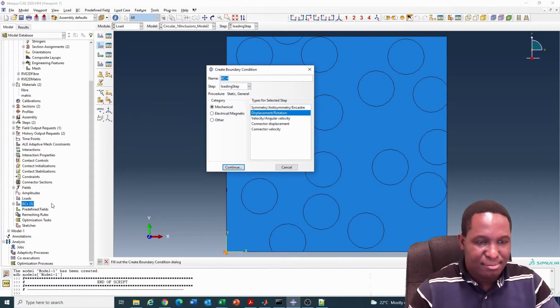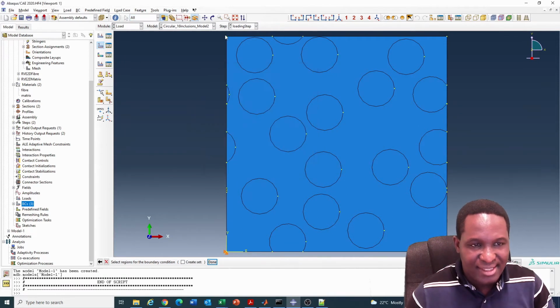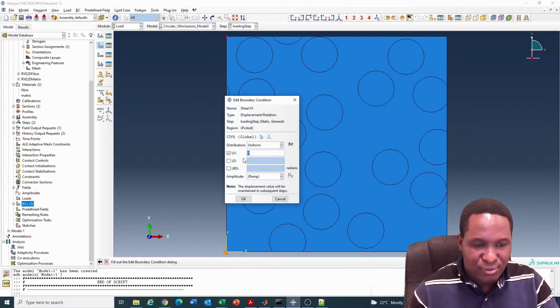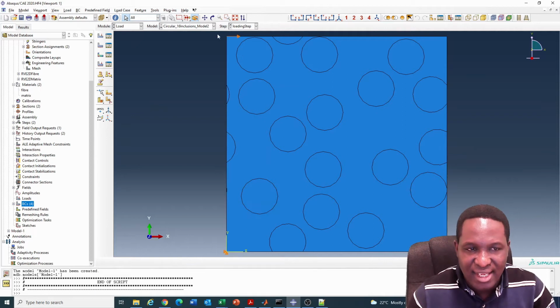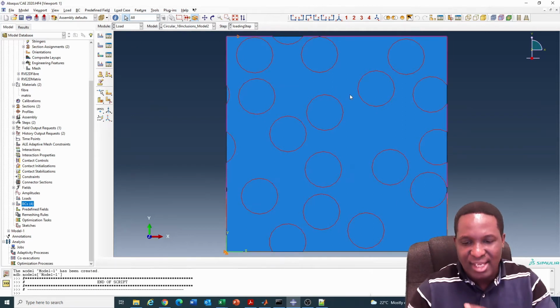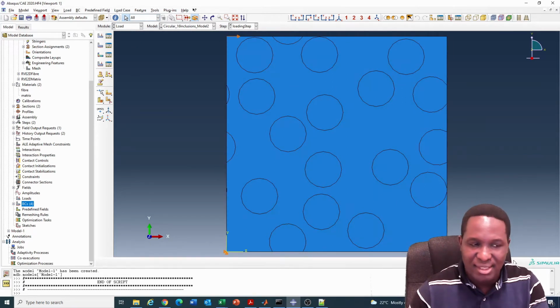Then the second shear component will be shear in the YX direction. This will be acting in the X direction, and it will be a value of 12. So if you think about what we've got here, we've got a case of pure shear and a tensile pull on this domain.